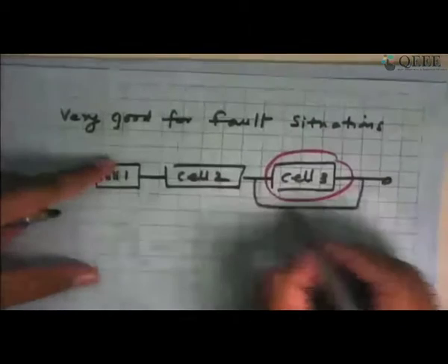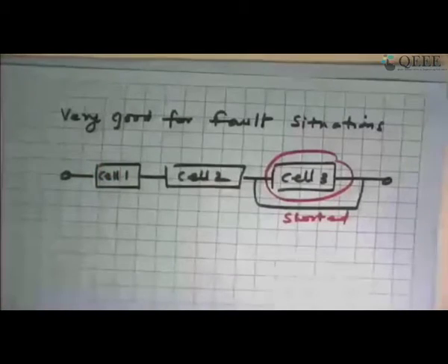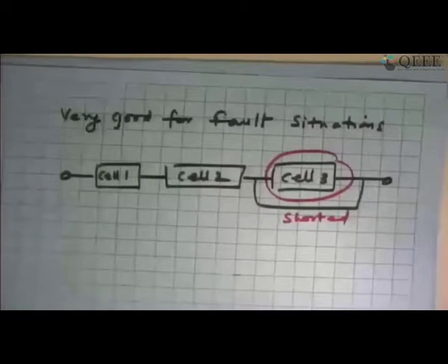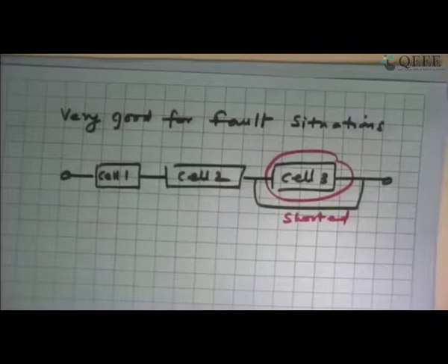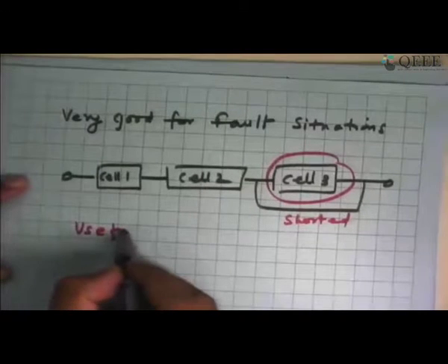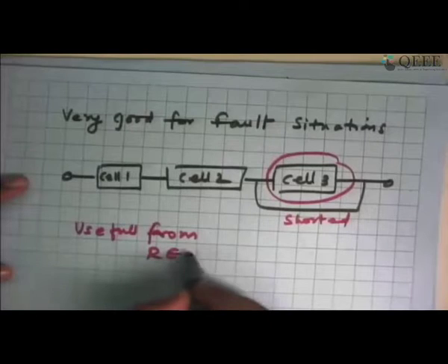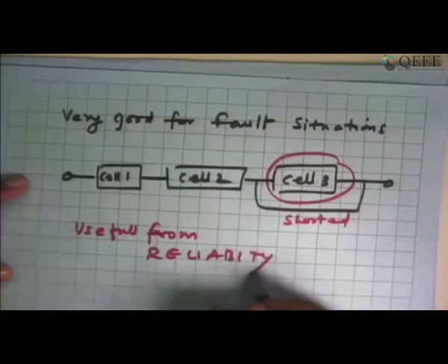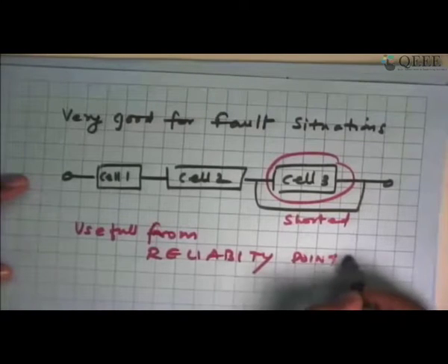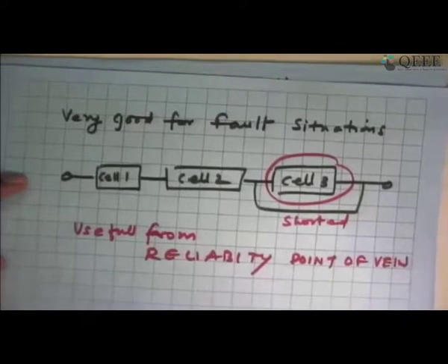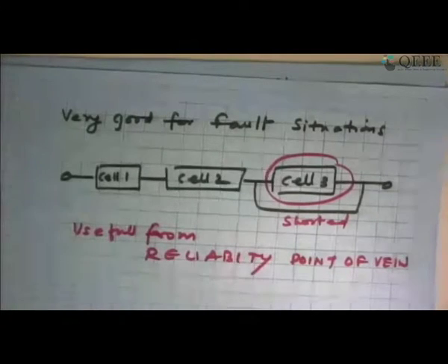So you may get a slightly reduced voltage, but still the inverter will keep working in the application. So from a reliability point of view, this kind of configuration is preferred, even though there is a complexity in the number of switches and all that.